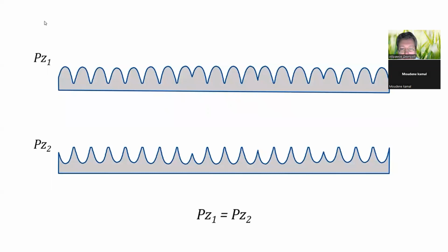Here, the two profiles have the exact same roughness amplitude. But if you had to walk barefoot on one of these surfaces, I bet you would prefer the surface above. Roughness amplitude alone is not enough to qualify the functional characteristics of the surface.